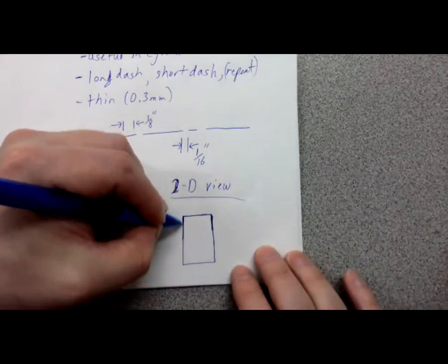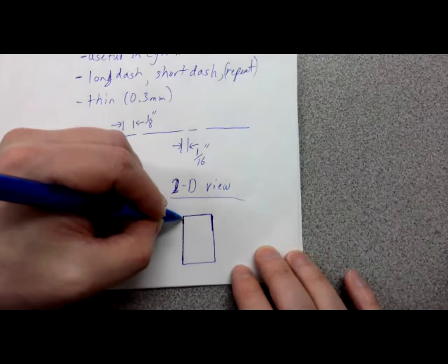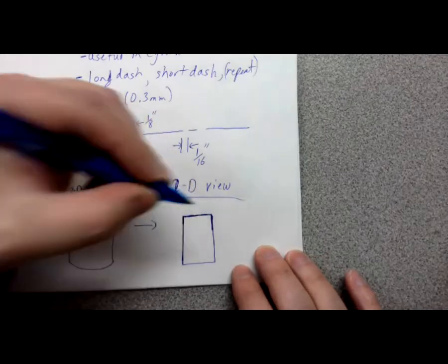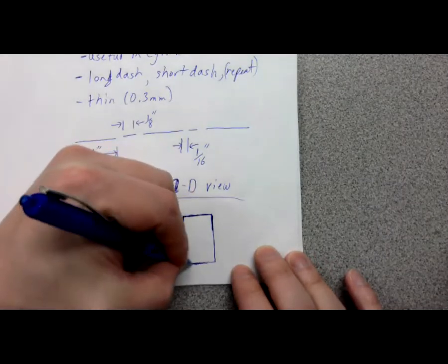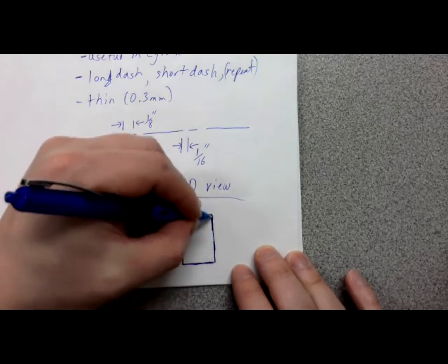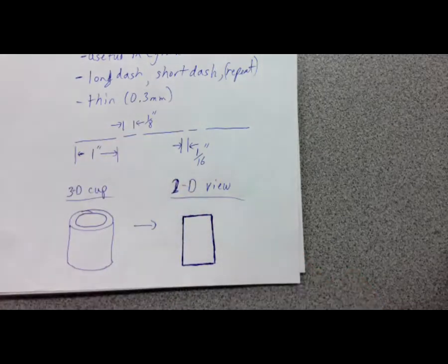Now, these are visible lines. So I'm going to go back in. If I'm on the whiteboard, I don't make lines thick until I've done all my lines, and then I go back and thicken them. If I'm doing it in pencil, I don't thicken them until the very end because I'm just going across it every time. With pen, if I've got a nice drying pen, this is a gel pen, then it's not too big a deal. You can thicken them as you go. So it's not super critical when you thicken the lines. Just make sure you thicken the visible lines at some point. Okay, so these are all nice thick lines now.